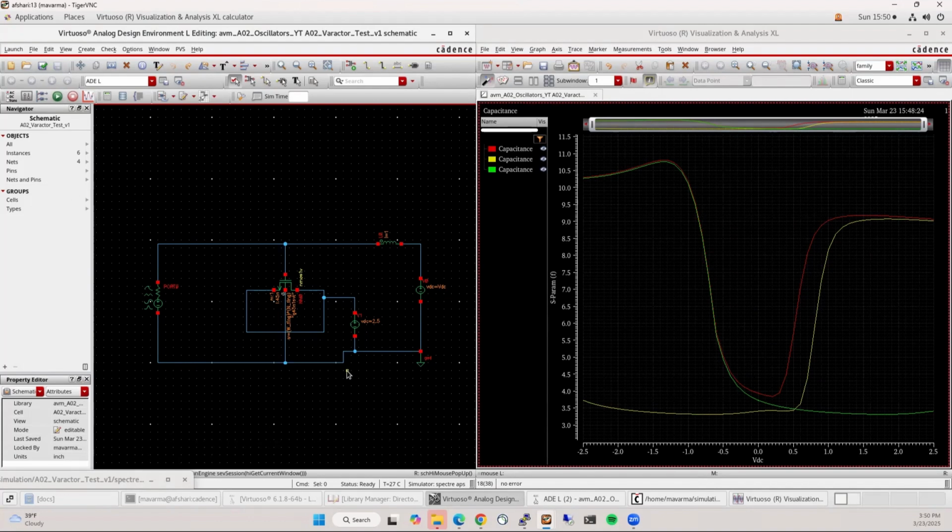And we haven't really done custom layouts or anything because you can't really verify that here. But in this PDK, unfortunately, there isn't a layout that I can show you of a dedicated MOS varactor that uses an accumulation mode PMOS device. But if you do have a PDK like that, then you can take a look at that and see that that's in fact the case, that what we discussed is that you can get rid of the drain source and you just have one body contact, and that gives you a really good performance.